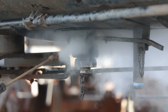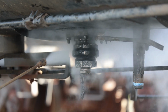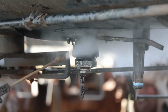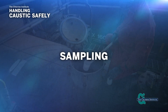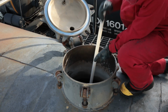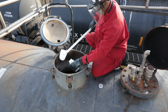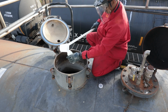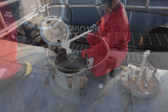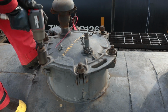Thermal protection should be considered to prevent burns from hot steam assemblies, and appropriate PPE should be considered to prevent caustic exposure from splatter. After venting off any pressure and opening the top manway, a product sample can be taken using a collection cup attached to an extension rod. After sampling, ensure that the container and sampling equipment is well rinsed to remove any caustic residue. Close the manway hatch prior to unloading a tank car or truck with pressurized air.